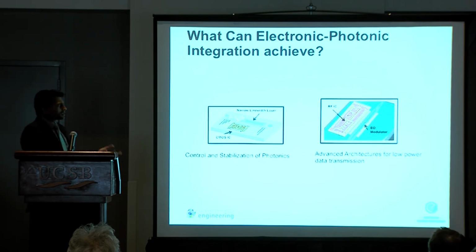We're also working on advanced architectures which help you have this intimate integration at the RF frequency. It prevents you from needing to do what is called matched design, which is a 50 ohm termination, so they don't have reflections. So that saves power. You can also distribute the driver so you can get better modulation characteristics because you get a better gain through the system. So these are the kind of things that we're trying to work on.